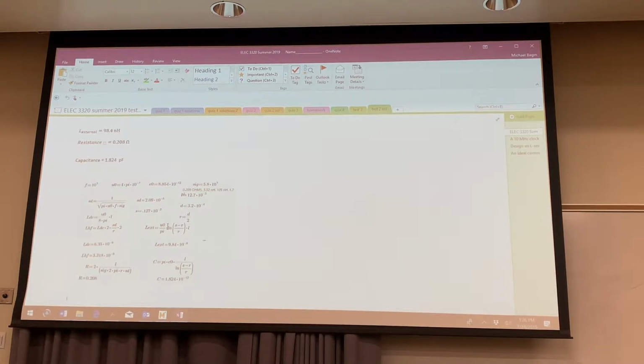Follow me on that? Some people, they didn't subtract the A from the second part. They didn't take separation distance minus A, and in some cases it doesn't matter. This one it kind of did. There was about I think a 5 to 8% error. Right? So that's right here. That's the external inductance. You all see this right here?